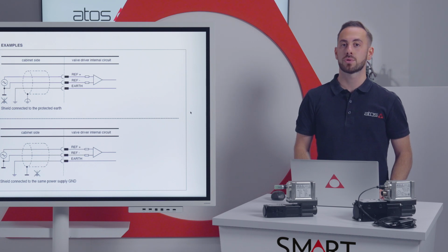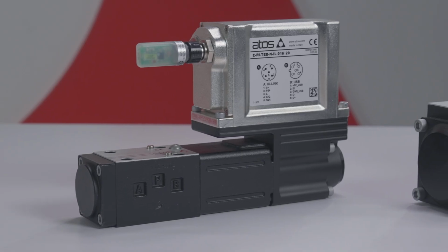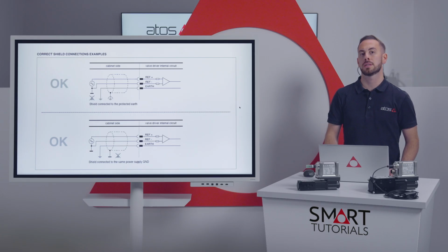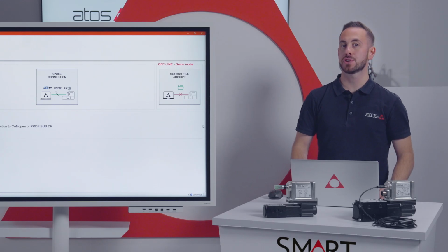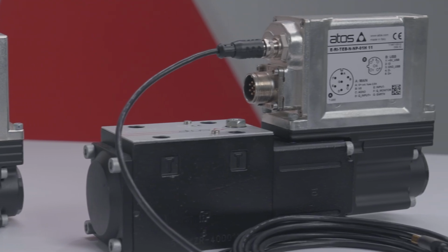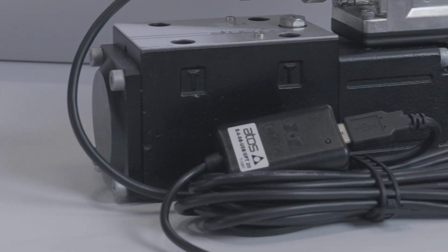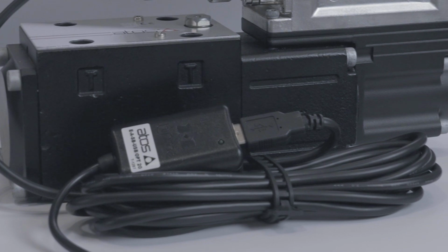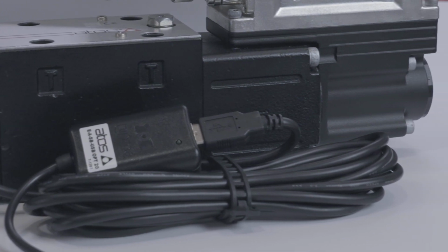It is therefore important to always separate the communication cable from power sources, like transformers, relays, inverters, or motors. A Bluetooth adapter is generally more stable in terms of connection, because it's immune to electrical disturbances, making it a better choice in particularly noisy environments. If you are using a USB serial cable, always ensure that you are using the optoisolator. This protects your PC from stray voltages in the system, and ignoring its installation can put your laptop at risk.